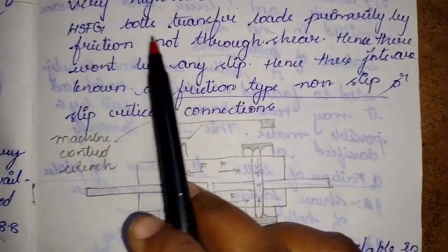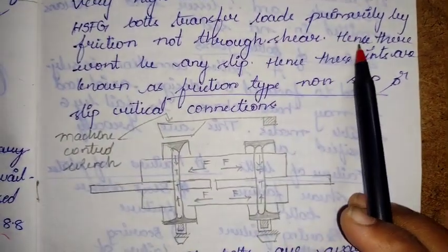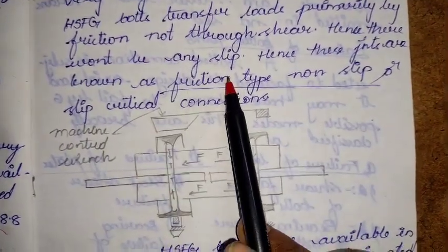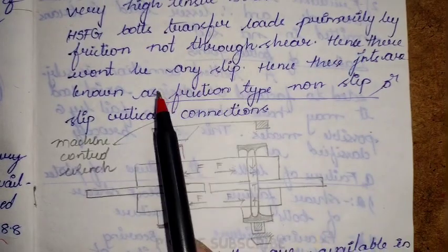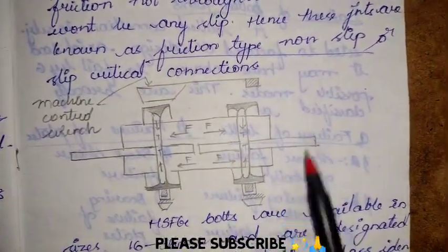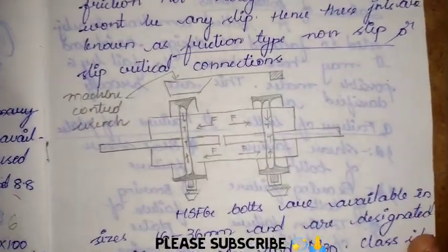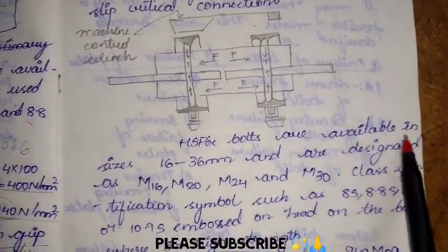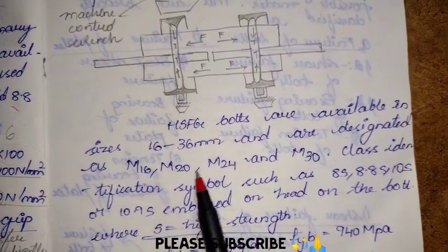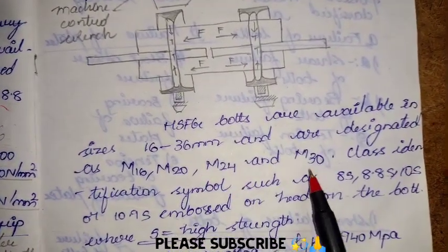And remember, HSFG bolts transfer the loads primarily by friction, not by shear. Hence there won't be any slip. Hence these joints are known as friction type, non-slip or slip critical bolts. This is the joint, and this is the HSFG bolt. HSFG bolts are available in sizes 16 to 36 mm and are designated as M16, M20, M24 and M30.